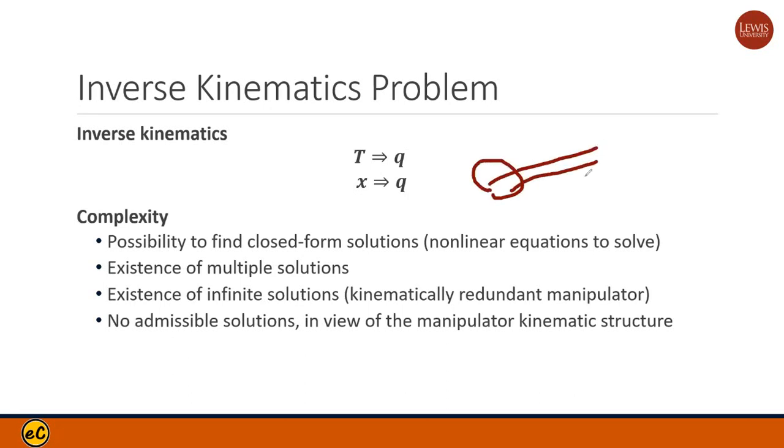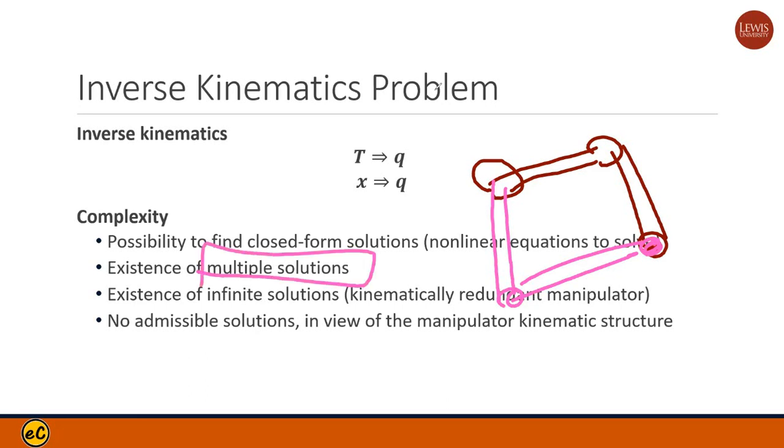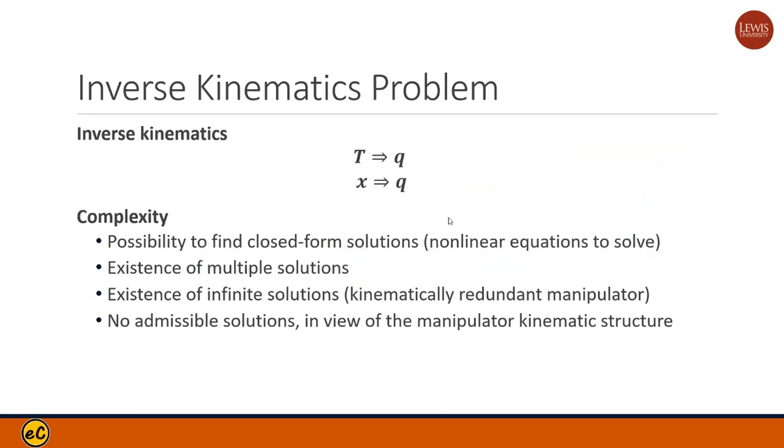Okay, so this one does assume that there are two joints, so you can bend this way to get to the point here, but you can also bend your robot arm this way to the same point. So multiple solutions of the different theta 1, theta 2 may exist. Okay, so trying to find the closed form actually takes a long time and may not be necessary.